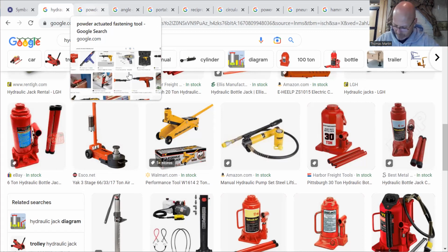Revision block. A revision block is located in the drawing area, usually in the lower right corner inside the title block or near it. Different companies put the revision blocks in different places. This block is used to record any changes or revisions to the drawing. It typically contains the revision number, a brief description, the date, and the initials of the person who made the revision. Okay, so number 35, the latest revision date on a set of construction drawings can be found inside the title block, which we already talked about.